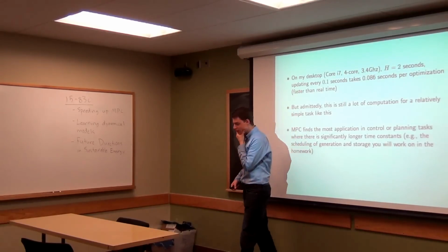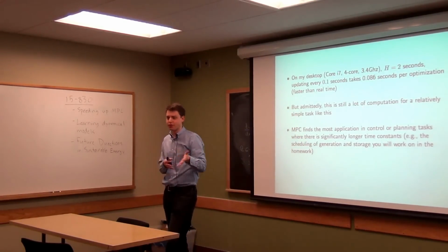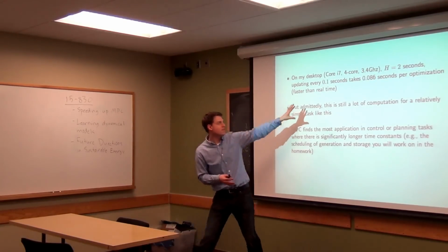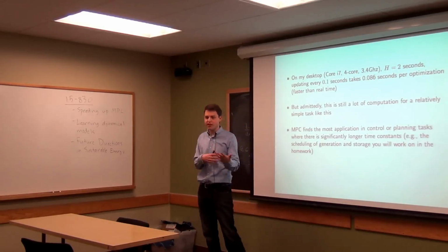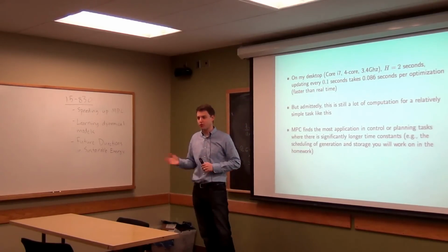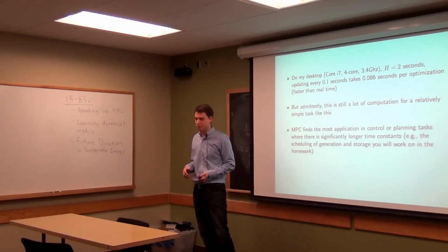Right. So whenever we can solve it faster than we want to update the system, I'm calling that faster than real time. And you really have to be in that regime to use MPC. Otherwise, on a real system, you wouldn't be able to.